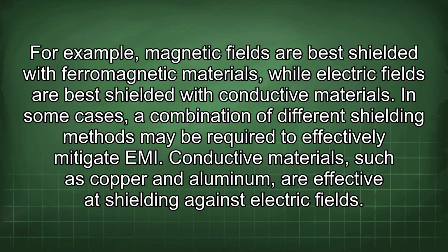For example, magnetic fields are best shielded with ferromagnetic materials, while electric fields are best shielded with conductive materials. In some cases, a combination of different shielding methods may be required to effectively mitigate EMI.